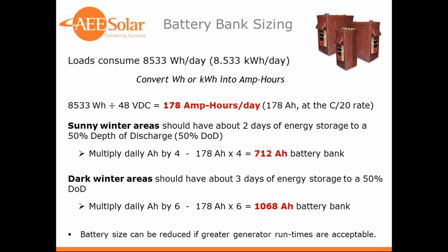4 or even 5 days of energy storage if you have a lot of extended storms. Batteries are expensive, however, so it might be more cost effective to just run the generator more for those extended times than it is to try to store the energy in the battery. And as I said at the bottom here, the battery size can even be reduced more than this if it's acceptable to have the generator run times be longer, to run it more often or for longer periods of time. But if we're trying to reduce the generator run times, we're going to want to increase the size of the battery.